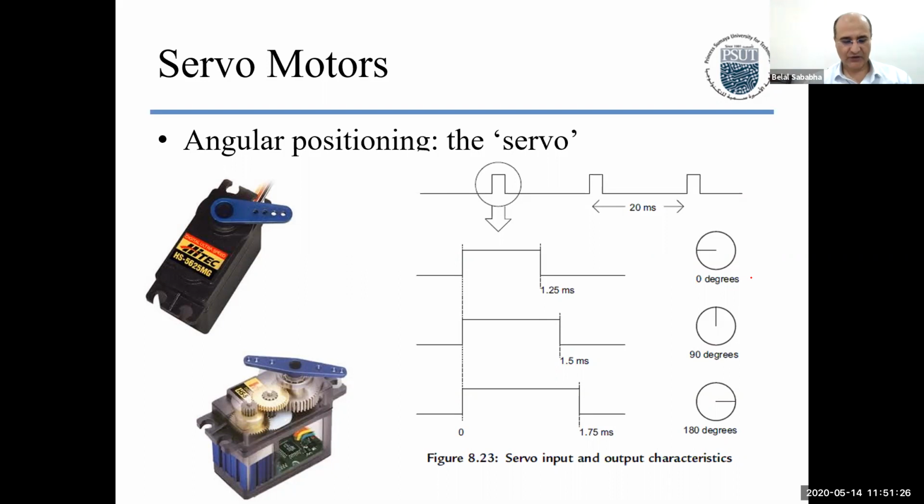The good thing about these servo motors is that they have a feedback mechanism. Inside this box, see, it's big. If you zoom inside here, inside there is a DC motor that moves something, and gears, and a potentiometer that knows how fast or the RPMs the motor moved, and it has a stop to stop it.